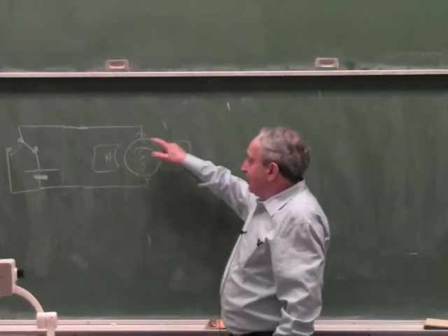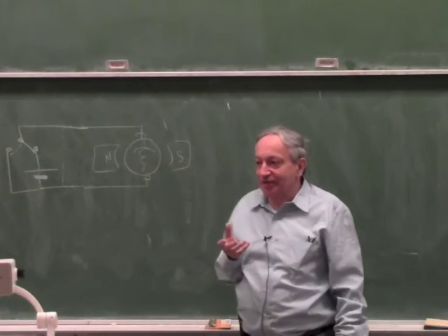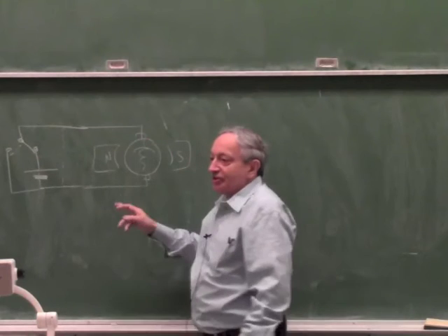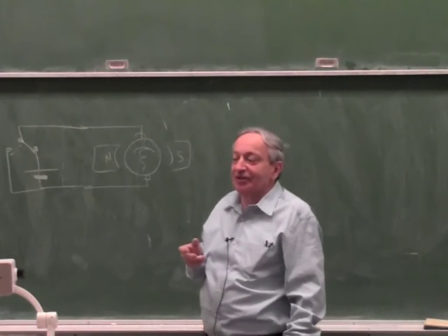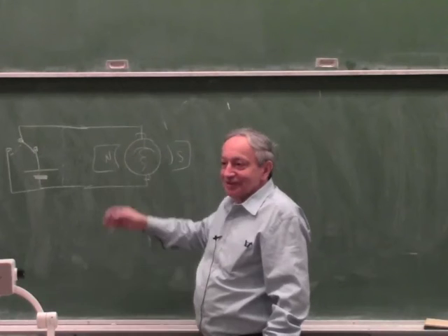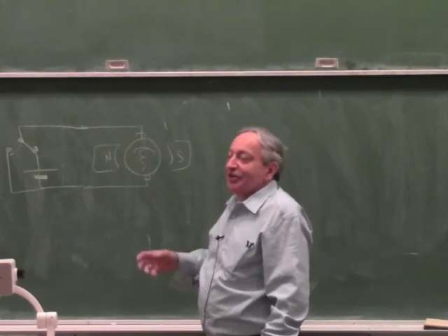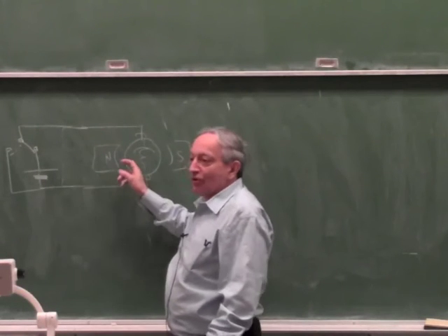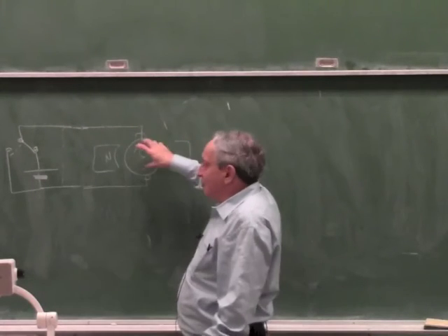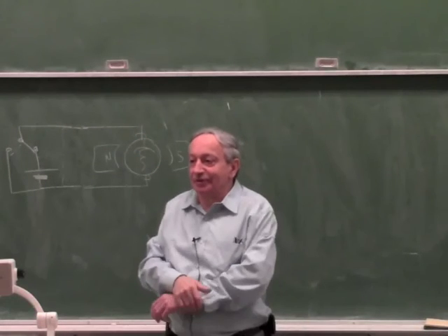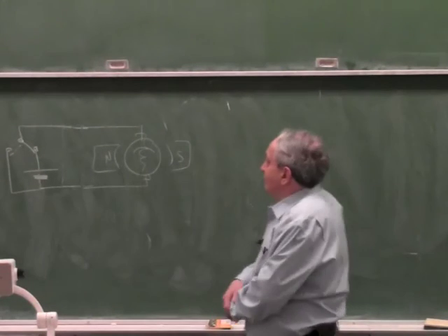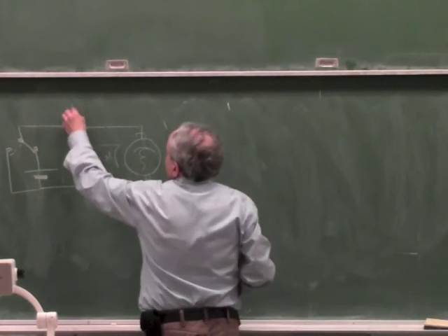Now, if this is spinning in a magnetic field, it's a generator. So the moment you connect it to ground, you are putting a short across a generator, then by Lenz's law, there is an induced current, it wants to stop. Basically, to make a current needs a torque. If you short it, it's making a huge current, so it needs a huge torque, and that huge torque slows it down very quickly. Is that clear? Good. So this is braking for PMDC.